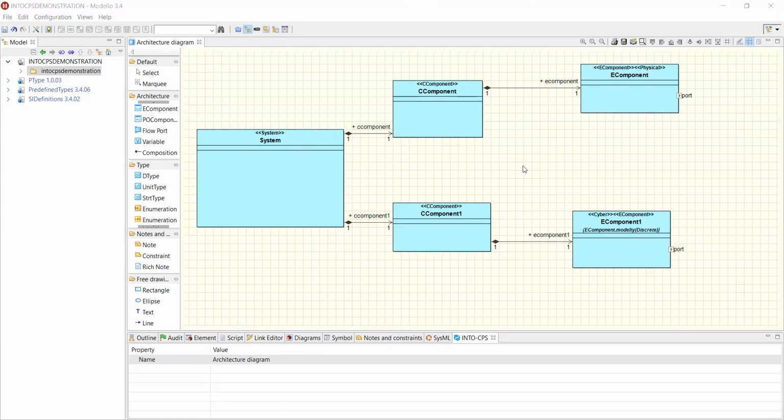The multiplicity, as in SysML and UML, is specified here. You got a little number here where you can specify min, max instances of this. So it's coming from UML and SysML. So you can specify that your C component is composed of 4 instances of this E component. That's mainly how you specify multiple instances.